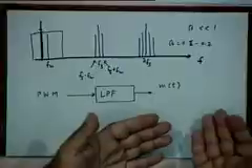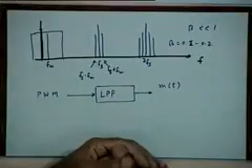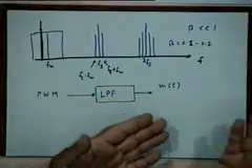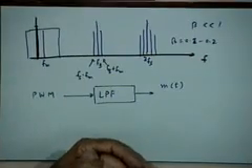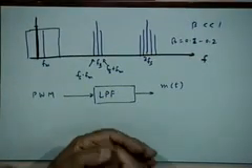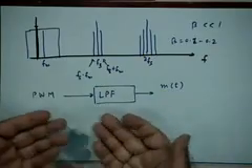No, all I'm saying is let it come. Eventually I can always remove a DC component by putting a coupling capacitor or something at the output, right? So let the DC component come. It will come if you have a low pass filter. The DC component will pass through that. So let it come. It doesn't matter. It doesn't do any harm to us. That's all I'm saying. I don't know whether you got your answer.